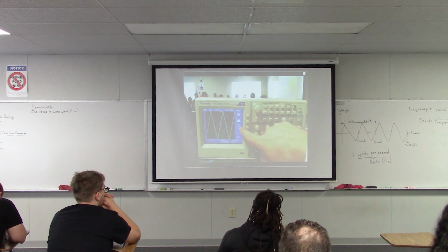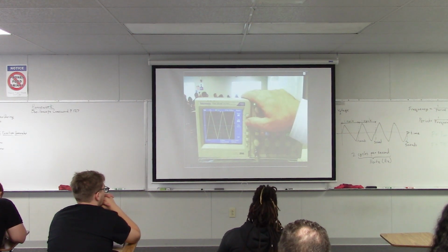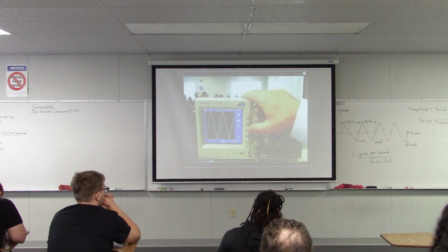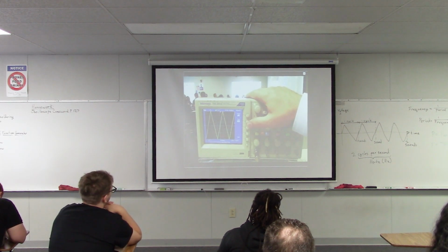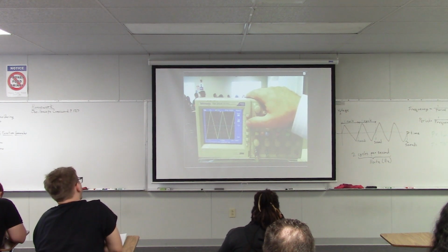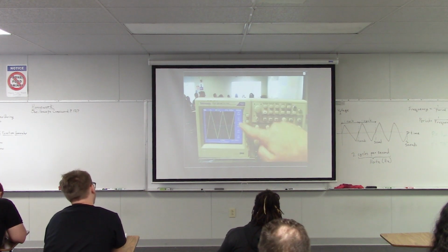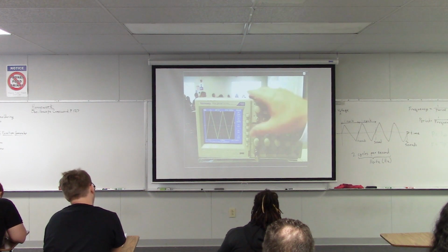So right now this is the period that's being measured. And then when you're happy with the type of measurement that you want, you push back, and now that measurement is shown in that spot. And if you want, you could go down to the next spot and choose a different type of measurement. So maybe down here we want the frequency. So now we're making those different measurements.